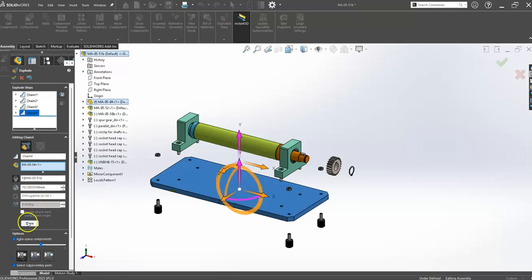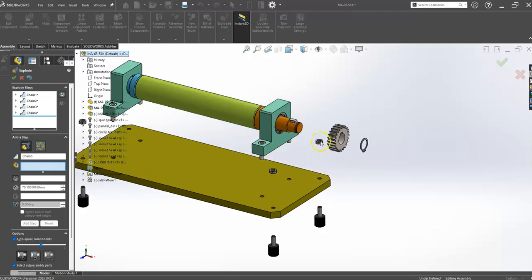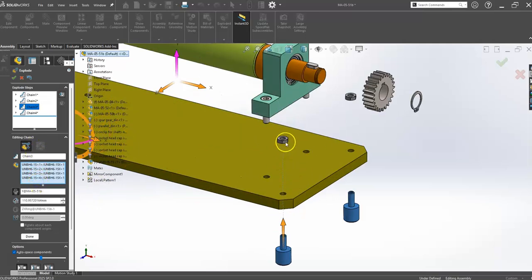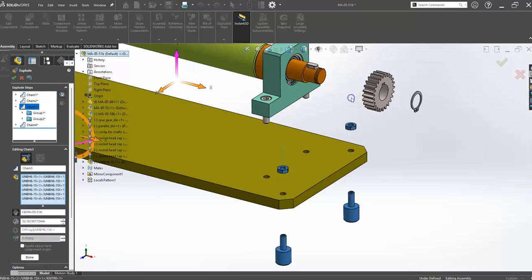okay, and hit done. Now I just noticed that I'm not dragging all the components in the sub-assembly. So for example, the feet had these nuts with them. So that's a good example maybe. So what I can do is go back to the steps here. So here's the first one, the second one, the third one. Okay, and you can see I've selected the 4 feet. I can go back in here now and select the 4 nuts that belong to them.